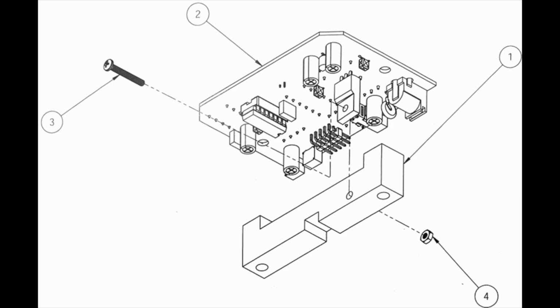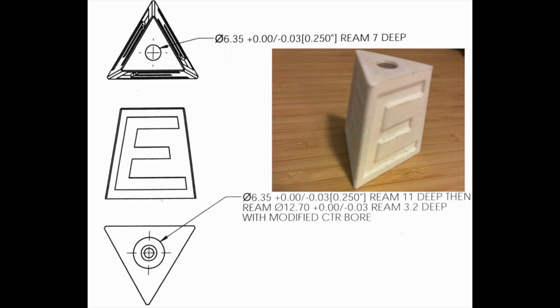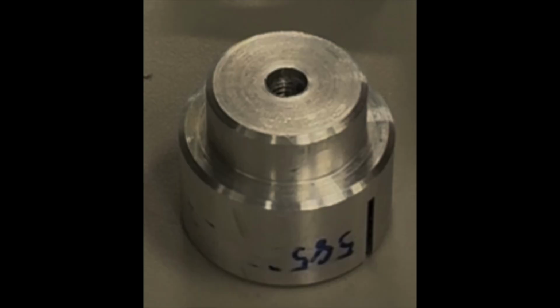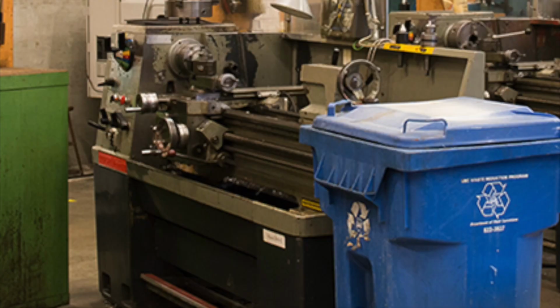While engineering drawings often start as handwritten, they can be translated into CAD files. These CAD files can be uploaded to CNC machines to produce solid replications of the drawn parts. Some parts, like this coil mount here, are machined using manual machines, such as lathes, drills, and mills. The coil mount was turned on a lathe, such as the one shown here. The lathe turns the part at a very high RPM against a cutting tool like carbide. The result is a fully rounded feature about a central axis.